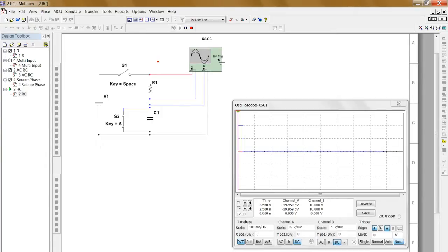What happened to the voltage on the resistor, I'm wondering? Why isn't that showing up? It should be in red because I have that red. So let's open that up again. And now I'll close switch 1. Oh yeah, now we see both of the voltages. And see what happened? I'll do that again now with the switch. I close the switch. The red is up, so now we're looking at all the voltage dropping across the resistor. No voltage is dropping across the capacitor. That's why we have 0 there.